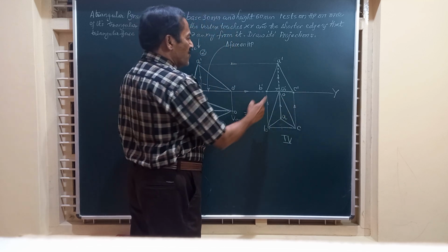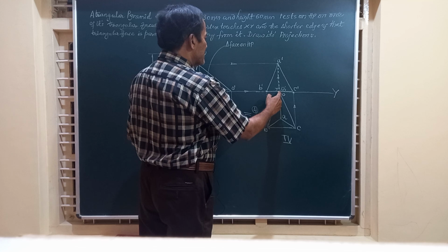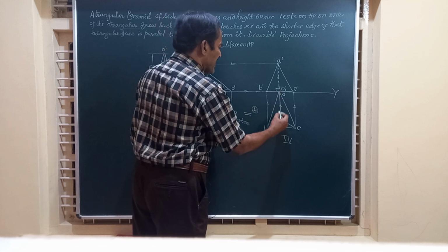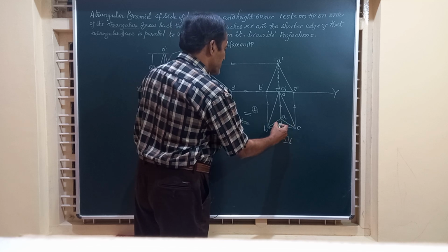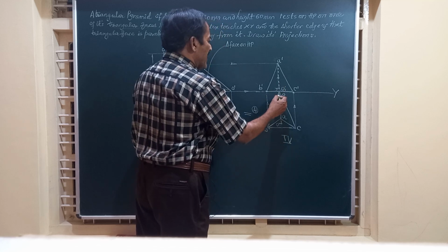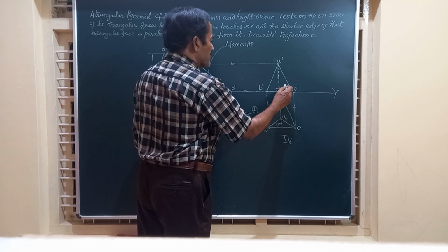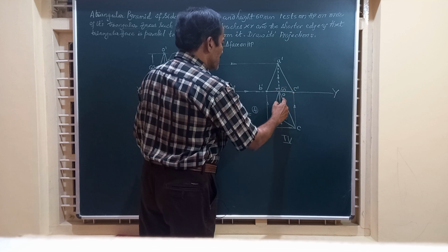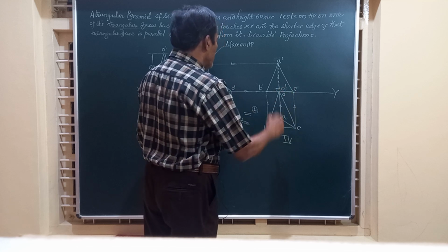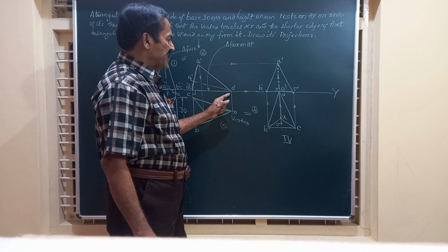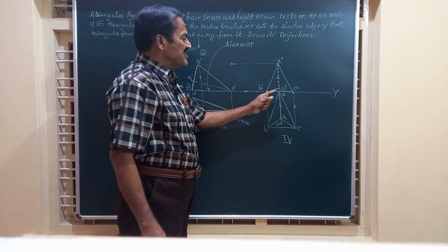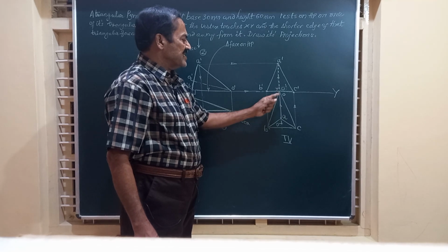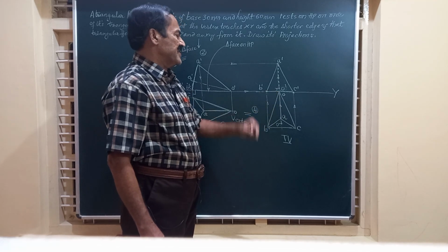Similarly, we obtain the point C dash. Now friends, O was a vertex. That vertex is here. So a horizontal line from O dash, and a vertical line from O, the center of the base. You are going to have this point O1 here. So this is O dash and this is O dash here, and you have this O here. Since this vertex O is touching the XY line, both in the top and front views, that is seen as a point there.